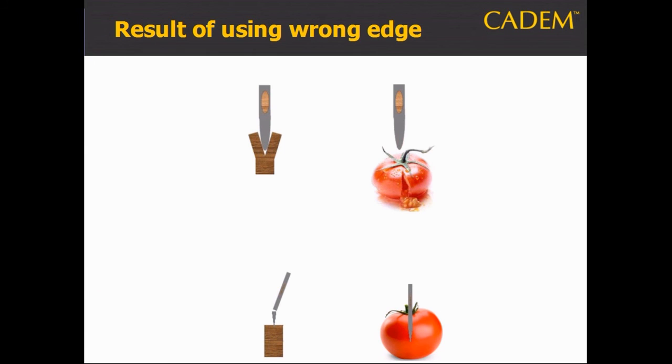Cutting tool manufacturers make inserts with different grades and chip breaker geometries for different workpiece materials and applications. So please remember this picture, and remember that you cannot just take any available insert and start cutting. If you want to reduce cycle time, get good quality parts, and make money in CNC machining, select the correct grade and chip breaker geometry from the catalogs of cutting tool manufacturers.